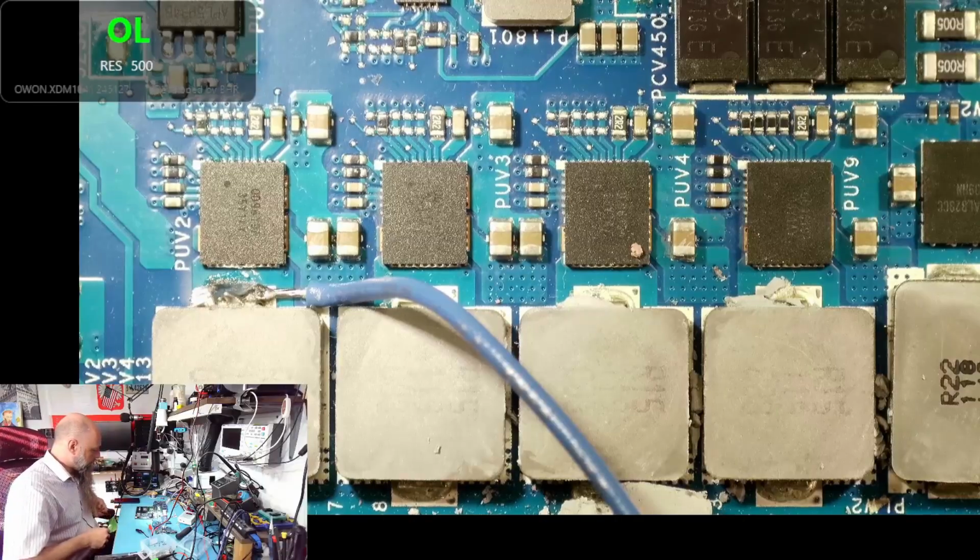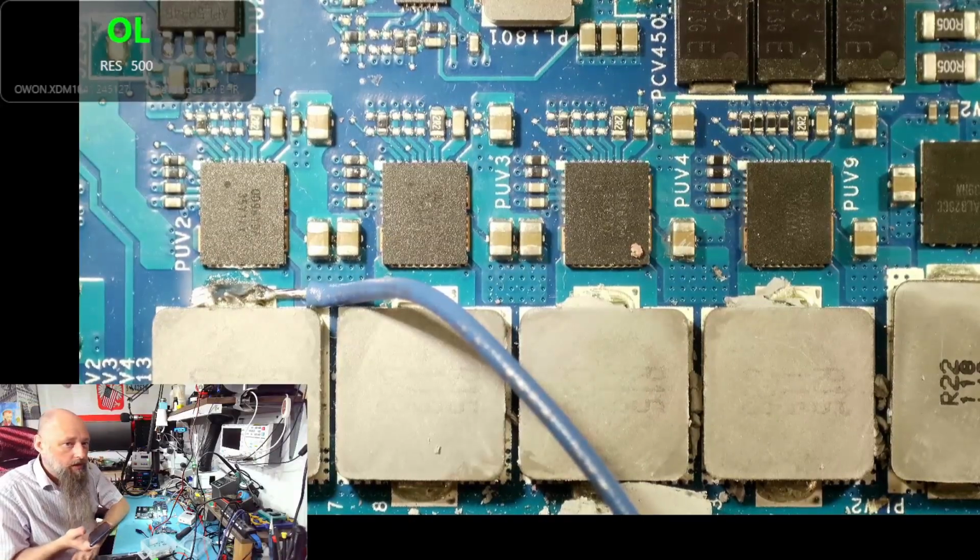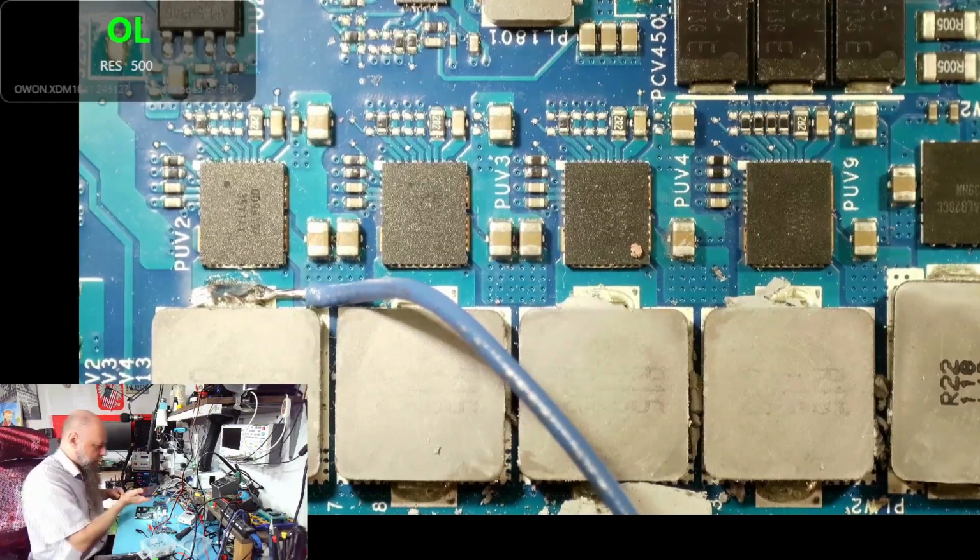We could lift the coils to just eliminate the GPU, but I did some measurements and it's not looking good. I was expecting, with a milliohm meter, you should be able to pinpoint which VRM is shorted. It should be relatively easy to confirm. I could not, which means it likely is not the VRM. But only one way to find out.